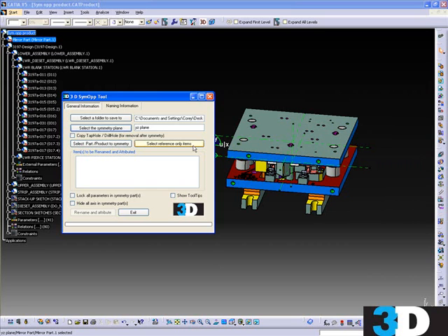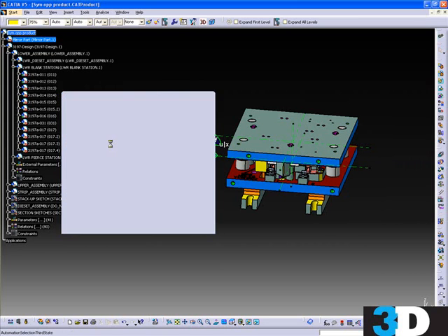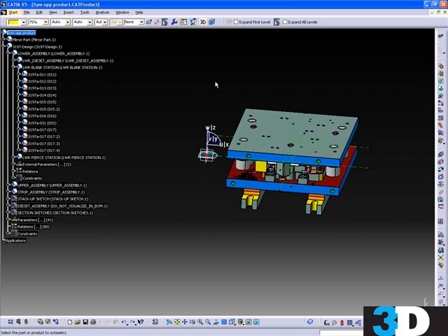That's nice because you can get positioning for components that can't be symmetried. You can still get the symmetry there and snap your component over to line it up for punch retainers and things of that nature. In this situation, we're just going to select the part or product to symmetry, and we're going to pick out of the tree, or we can window it if we want to, but I like to just pick right here out of the tree the whole design.